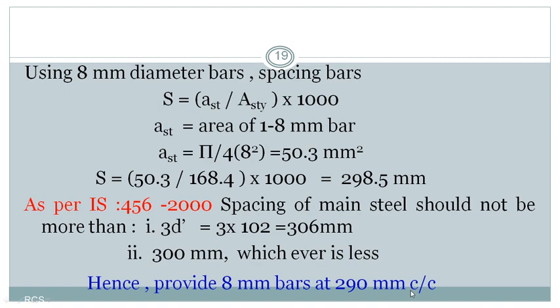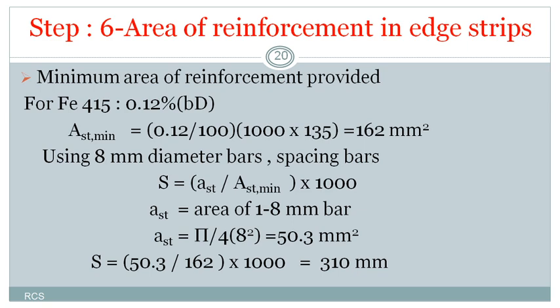So I think you are clear on how to provide the area of reinforcement along the x direction of the middle strip and the y direction of the middle strip, and what spacing is to be maintained for those two conditions. After knowing that, we go for the calculation of the area of reinforcement in the edge strip.